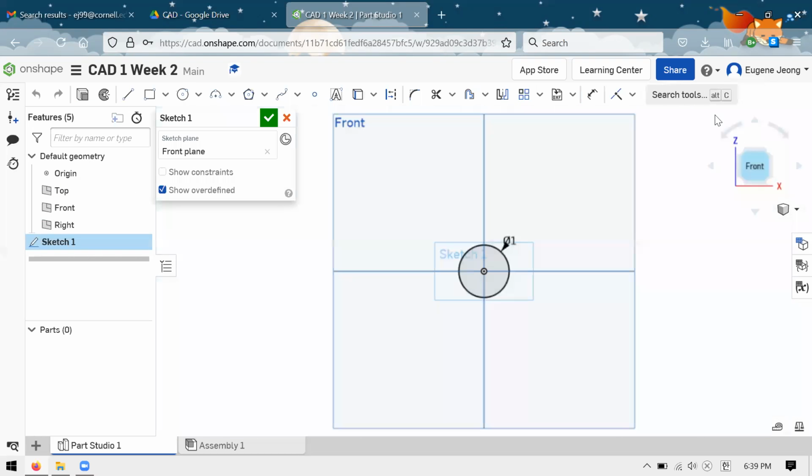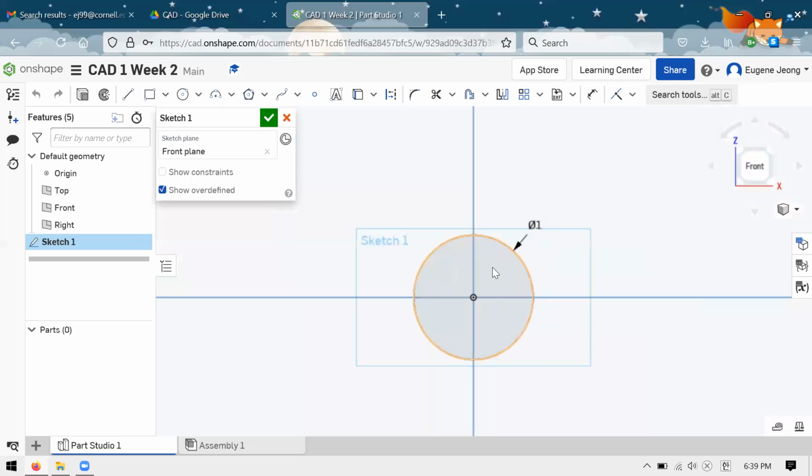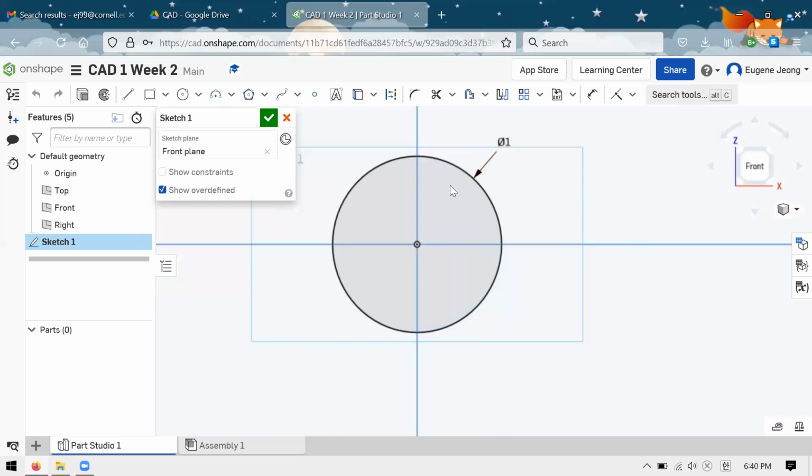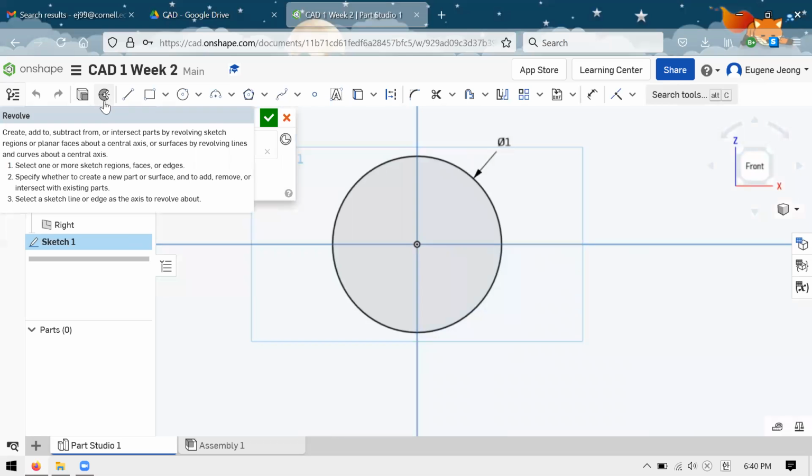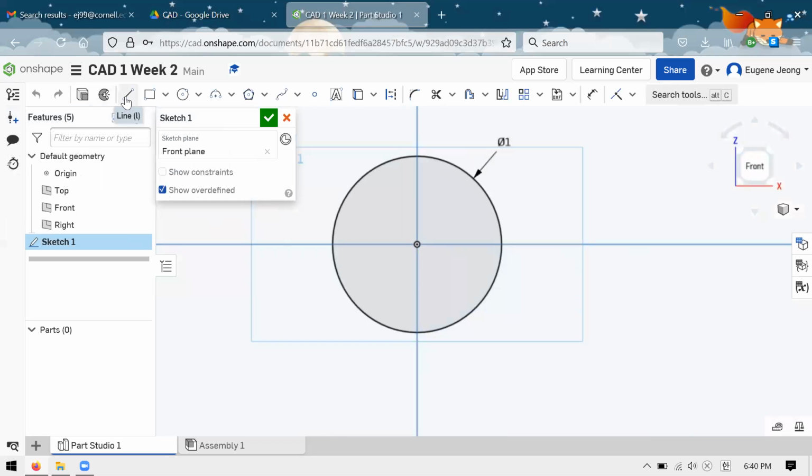And what I'm going to introduce to you to achieve our first problem of making a sphere is the revolve tool. And you can see when you're in your sketch tools, they also show you two 3D tools. One of them is extrude, the other one is revolve. So it's very important. And we'll get right into it.